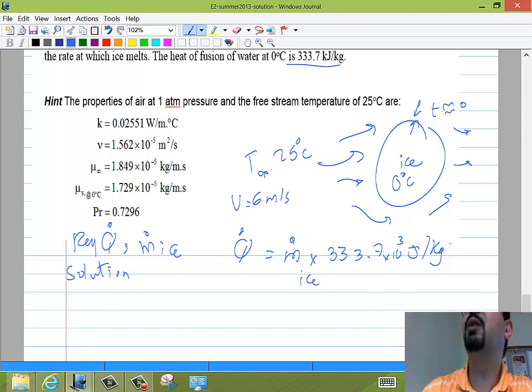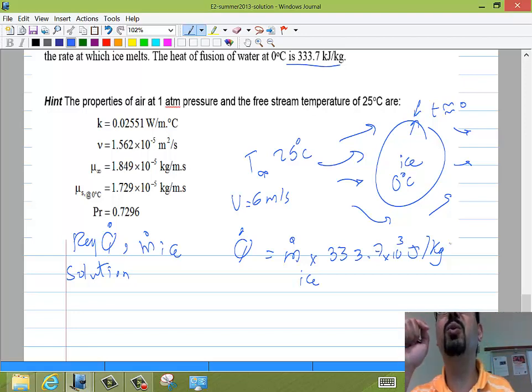All the joules going to the tank, what will the ice do with it? It cannot just go from 0 to 1 to 3 to 5 degrees. It first has to turn into liquid before it starts heating up. So as long as there are two phases, ice and water, it will have to melt first before it can take the water and the ice to 1 degree. However, you can cool it, so that ice at 0, if you cool it, will go to -1, and it will get cooled to -2. It wouldn't mind. It would not say, no, I have to become water first. No, it's ice, it can go down. But it cannot go up before it turns itself to water first.